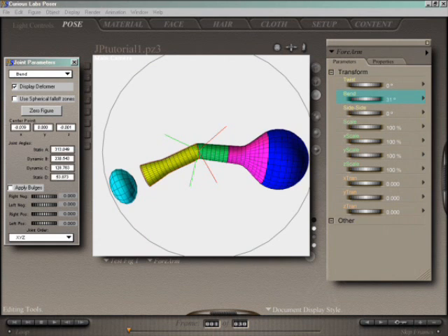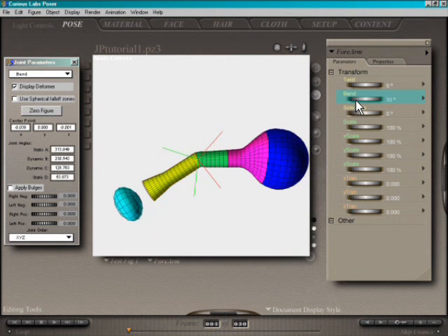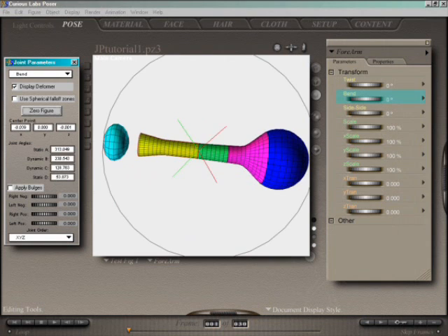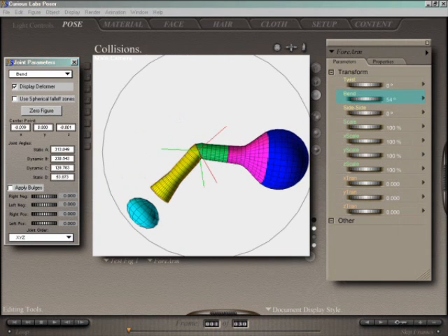That's the blend zone. I'll give it a move. Zero the figure. We can simply alter by dragging on the ends of those planes to give variation. If I do this and then drag down here, you'll see how that changes the way the joint is formed. There we've got a smoother angle on the bend.